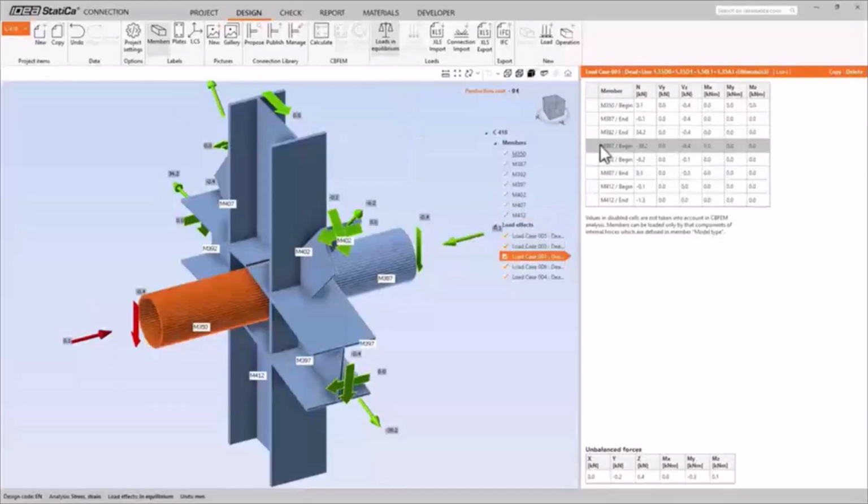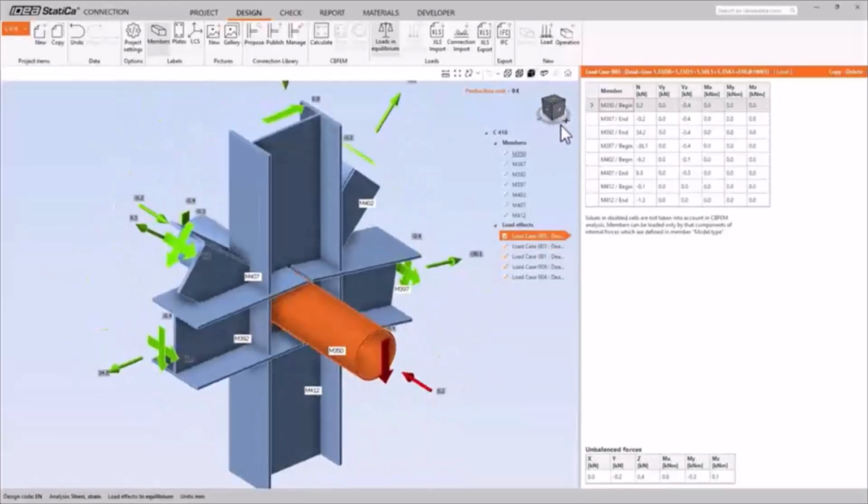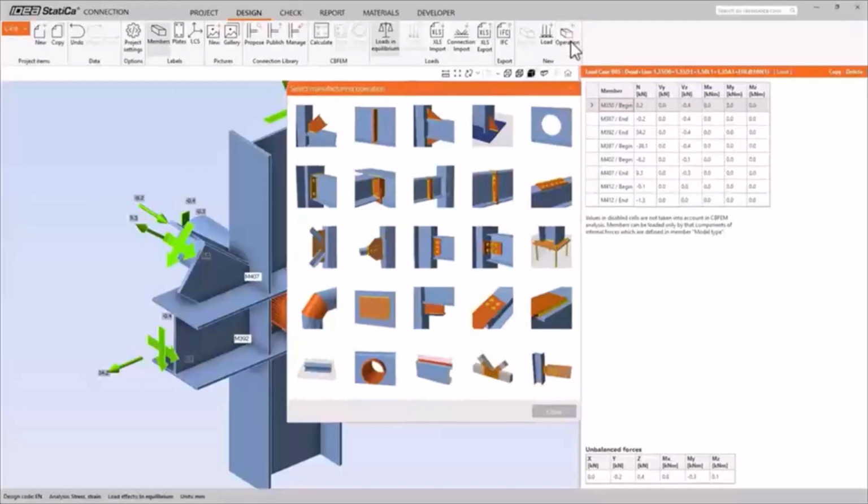And as you can see, part of the process of transferring these allows us to look at the load effects or the actual combinations, and we can evaluate the critical load effects. So yes, you're going to end up with a lot of load case combinations when you do your global analysis, but we have algorithms as well as MasterSeries to further refine those load effects into a smaller subset of critical load effects, which is exactly what you need.